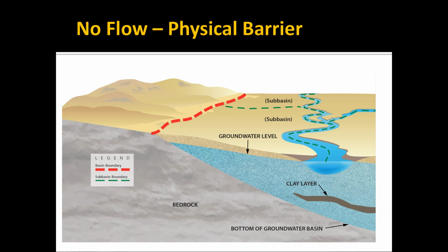It could also be a really low permeability fault. Could conceivably be a no-flow physical barrier, but some sort of bedrock outcropping, or just an extremely low permeability unit that differs by several orders of magnitude in hydraulic conductivity would be another kind of physical barrier.